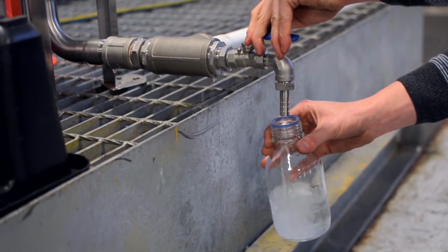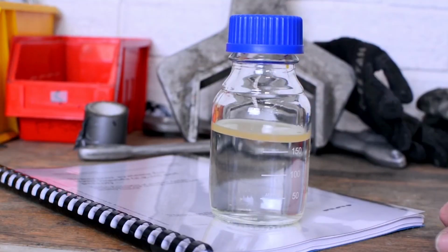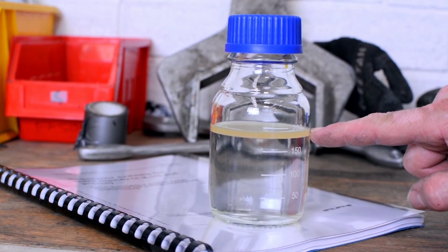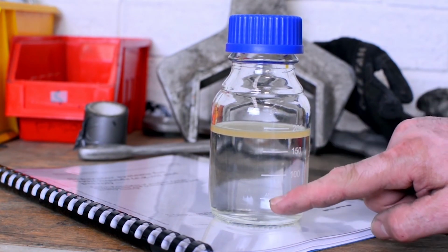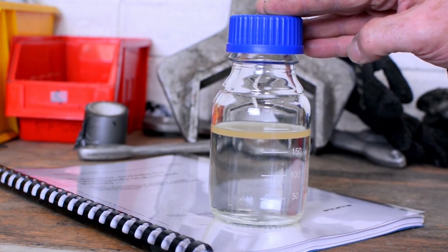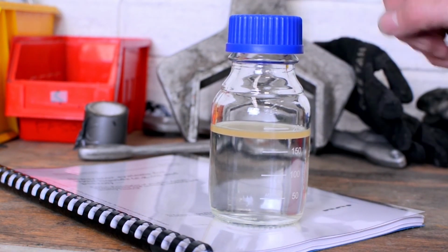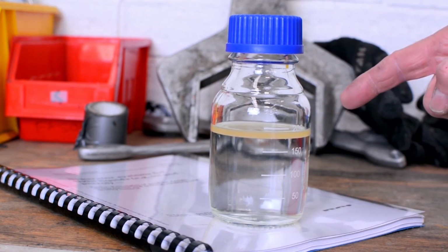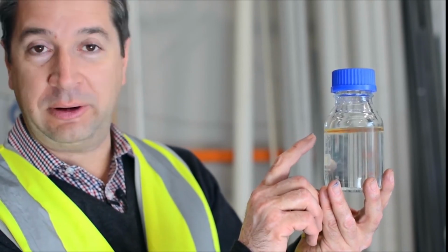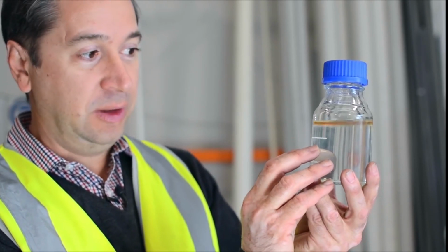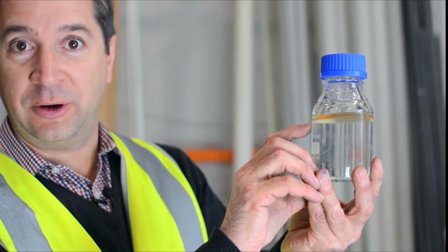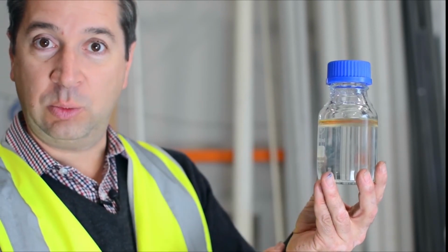determined using this sample. The sample here is generated using the European standard, and as you can see, there is a fairly clean oil layer, and the water underneath is also fairly clean. And that's really representative of an oil spill rather than an industrial application, where you don't have any chemicals or detergents or any mixing of the oil with water. Using the European testing method, there's not much mixing between the oil layer at the top and the water layer at the bottom. So if you were to take off the oil layer at the top, there wouldn't be any emulsified oil, so you would just be left with clean water.